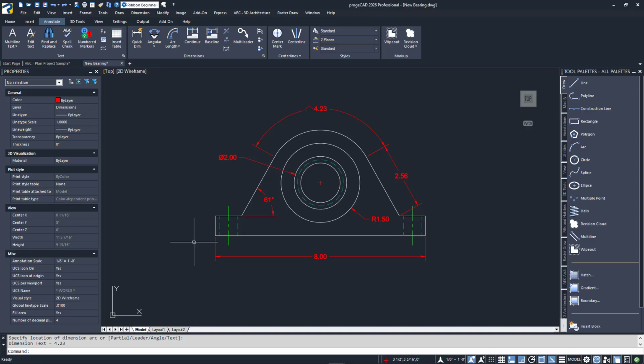That's pretty good, but I didn't get the two hidden holes on either side. To demonstrate two dimensioning styles, I'll erase the 8-inch base dimension and demonstrate both. These are called continuous and baseline dimensions, and both start with an existing dimension.